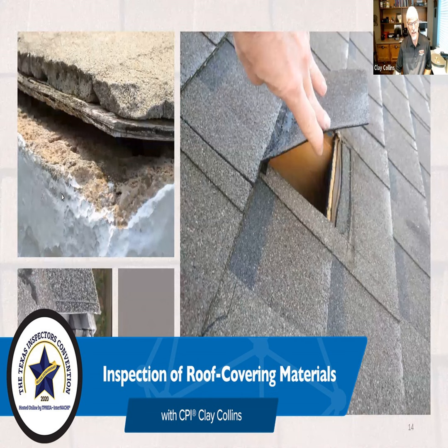The time that you see this really causing damage is during the installation and the removal and replacement of a roof cover. Because it's so weak, most of the times you see that the installers load the roof by just laying the shingles on top of that. So they put a lot of weight on this little narrow, broken, or weak board. And then when they re-roof, they use the shovel to remove all the shingles.